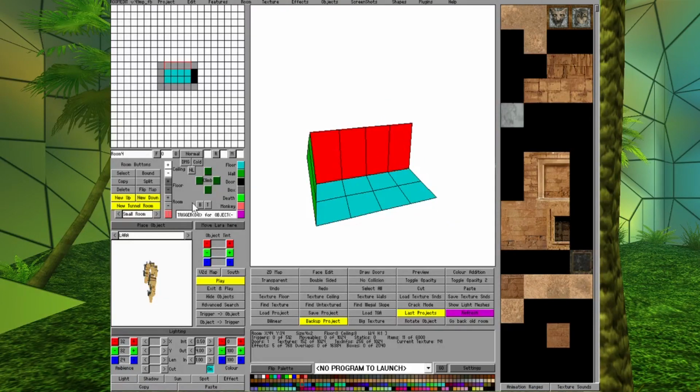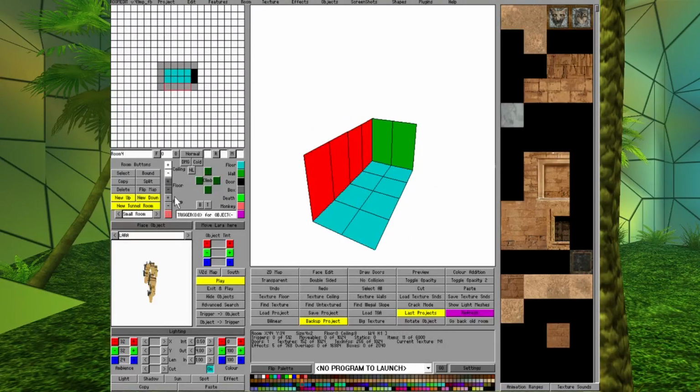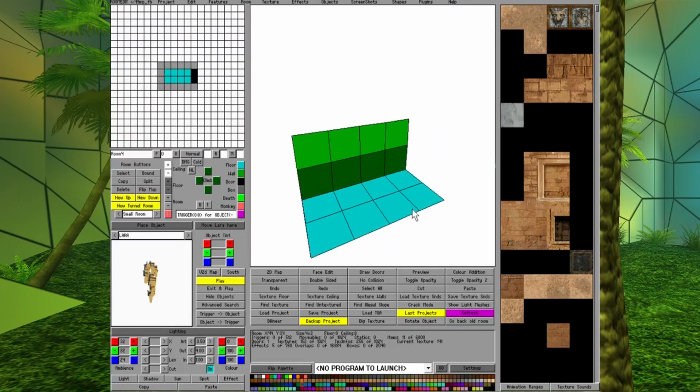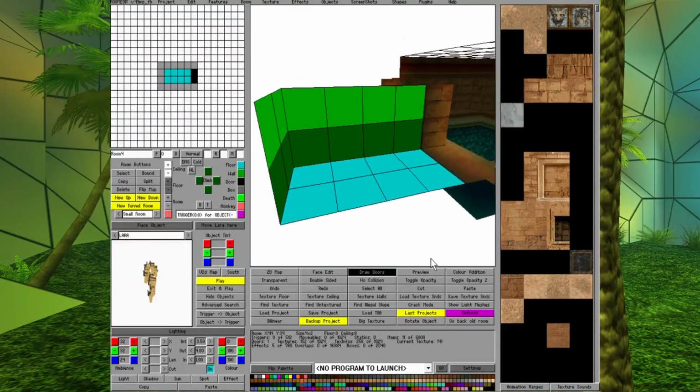So what we're going to want to do in here is use the wall grids. I'm just going to do them manually, because if you press F12 when there's a door in the room, it messes up the door. It puts a grid across the door as well, and we don't really want that, so it's easier to just do it manually, and it's only a small room anyway.